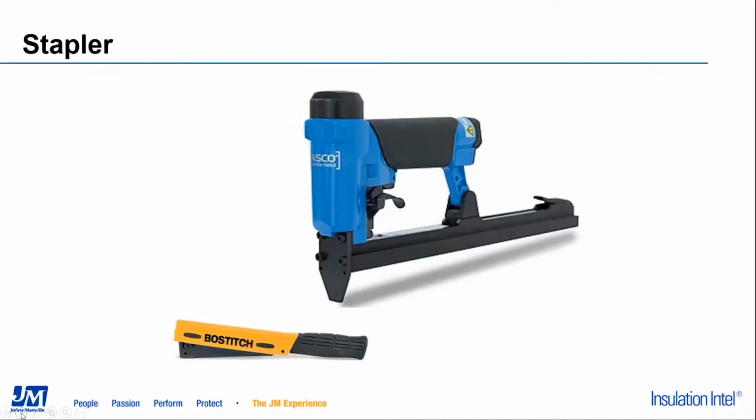Staplers are used to attach the fabric to the wooden studs. These come in a wide variety, but the most commonly used for this type of application are pneumatic variable rate staplers. These staplers allow the installer to hold the trigger down and move along the stud face, continually applying staples. In using these types of staplers, it is important that we adjust the rate of stapling so that we are achieving approximately 1 staple per inch. The adjustments on these are usually a dial or lever on the stapler that we can set to achieve the desired result. We also want to make sure that we're using at least a 1/4 inch stapler so that it properly fastens the netting to the wall.